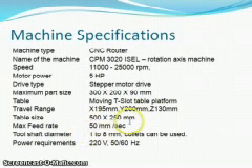The table size is 500 by 250 mm. Maximum feed rate is 50 mm per second. The tool shaft diameter is 1 to 8 mm. Collets may be used for different sizes. The power required is 220 volt, 50 or 60 hertz.